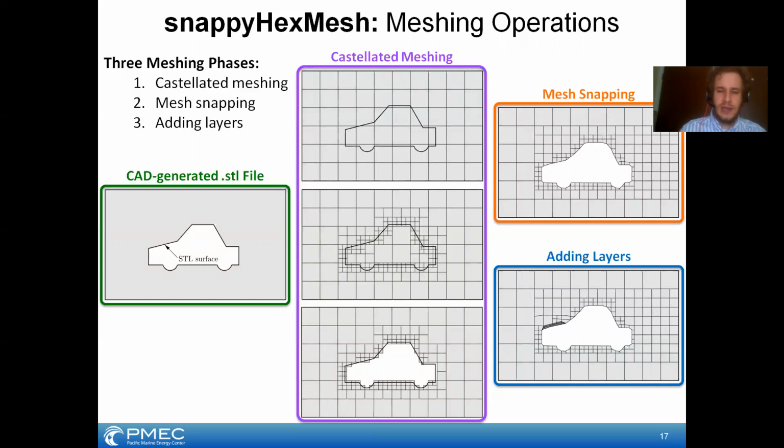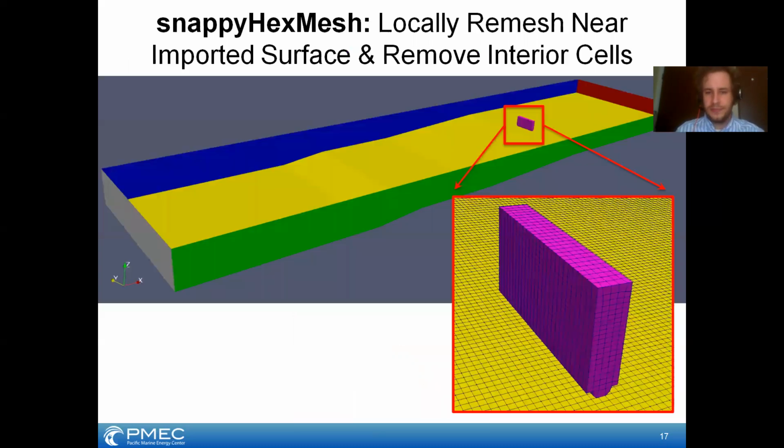There are other alternatives to snappyHexMesh. You can use foamy-HexMesh within OpenFOAM, or of course you can import meshes from other software. The foamy-HexMesh tool is kind of like a cousin of the polyhedral meshing in StarCCM+. It's essentially the same process, but with a different type of cell shape it's going for. And the result of such a process would be like this. You get the flap imported into the domain, and the mesh fits around it nicely.